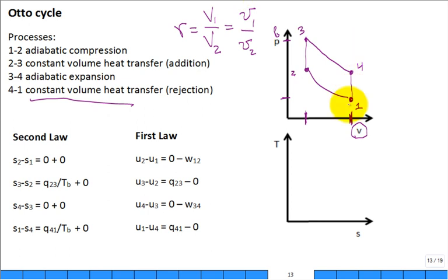You could add a little notation like this. What are they indicating right there with the little dash hash mark? Adiabatic, right? Yeah, there's no heat transfer, like insulated, adiabatic. And then they could also write something like this: S equal to C. You can't fool me. S is equal to S, C is equal to C, but S is not equal to C. No, entropy is constant. That's right. And then here they put a little Q in, and right here they put a little Q out. They know that, oh, from 2 to 3, that's heat addition, and from 4 to 1, that's heat rejection out of my cycle.